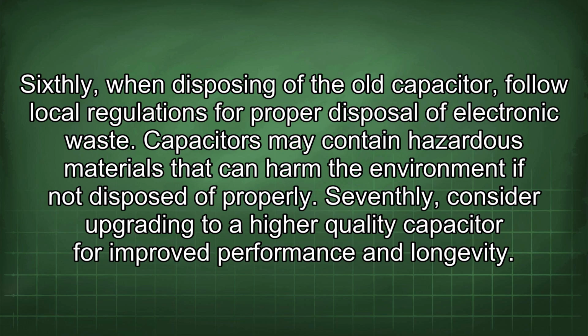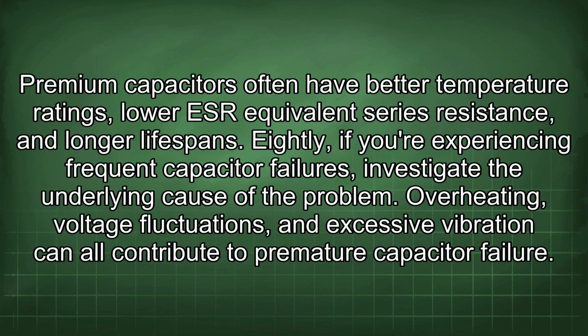Sixthly, when disposing of the old capacitor, follow local regulations for proper disposal of electronic waste. Capacitors may contain hazardous materials that can harm the environment if not disposed of properly. Seventhly, consider upgrading to a higher quality capacitor for improved performance and longevity. Premium capacitors often have better temperature ratings, lower ESR (equivalent series resistance), and longer lifespans. Eighthly, if you're experiencing frequent capacitor failures, investigate the underlying cause of the problem. Overheating, voltage fluctuations, and excessive vibration can all contribute to premature capacitor failure.